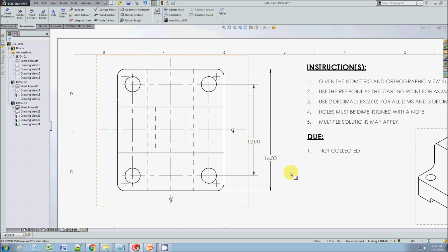So what's nice about this is that the error is symmetrical. Okay, if there's machining error, it's symmetrical. It's not biased towards one side of the machine. So this is why when I see a symmetrical object, I take advantage of this and dimension like this, because it's so much more effective.